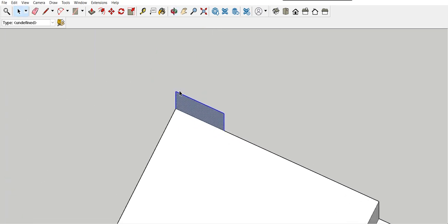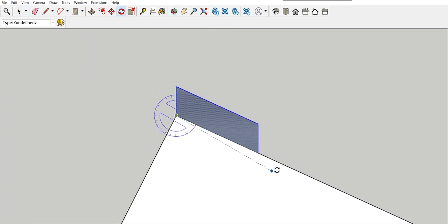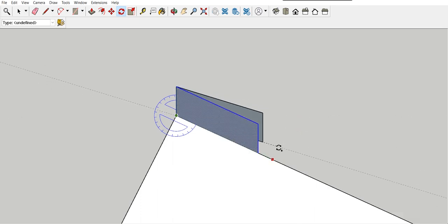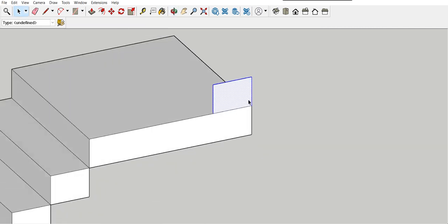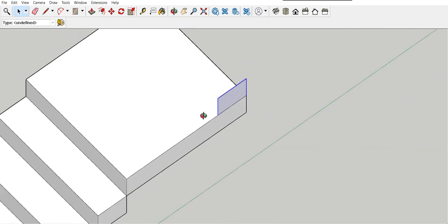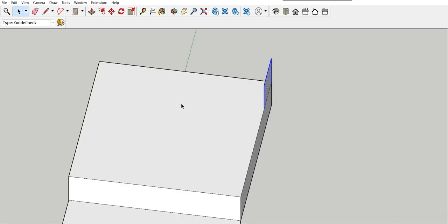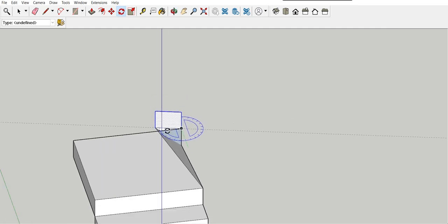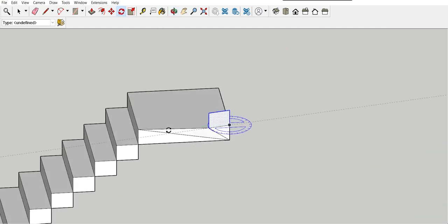Then you can rotate this with Q. Now you can see, if I am not hitting the Control key for the rotate command, what is happening? Now this rectangle is merged with the landing rectangle. So what will happen when I simply rotate this? My geometry will get distorted. My entire geometry is getting stretched along with this rectangle because both these rectangles are merged.